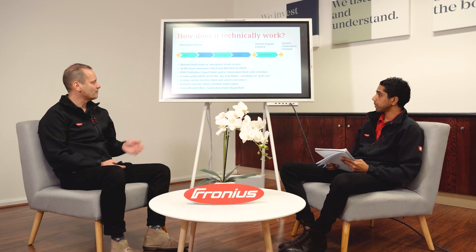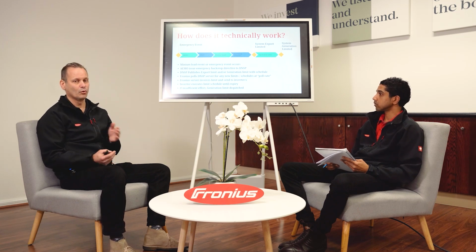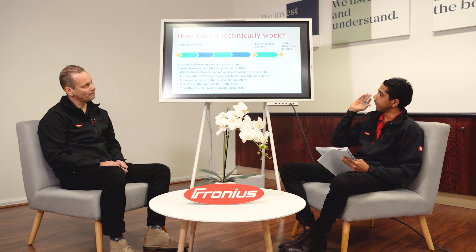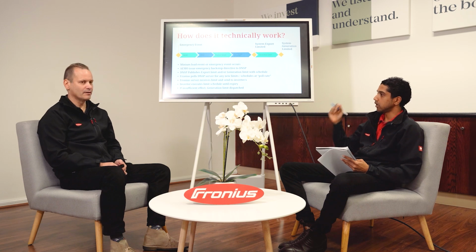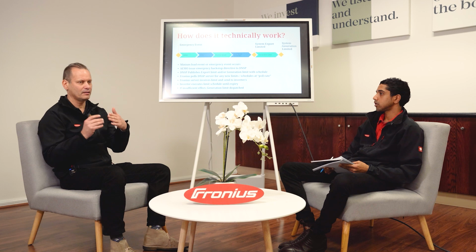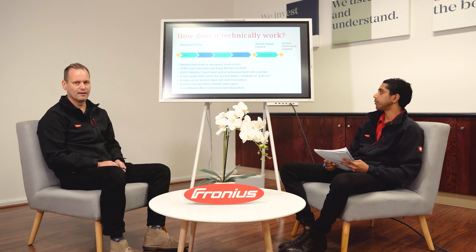Some things to remember here: the schedule that is sent to the inverter is stored on the inverter. So if you switch the inverter on and off or reboot it, it will stay on the inverter and it'll execute it and do whatever it needs to do with the schedule. And Rod, you can have overlapping schedules, right? Correct, yeah. They can have overlapping schedules, and depending on the priority of those schedules, that'll determine which one is executed first, etc.